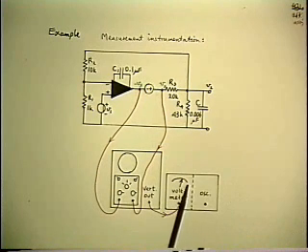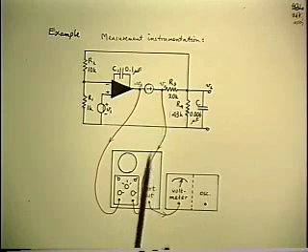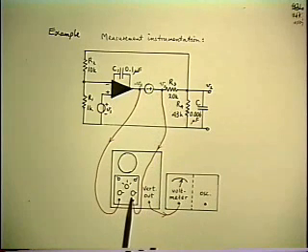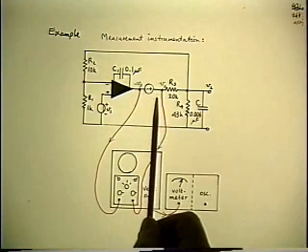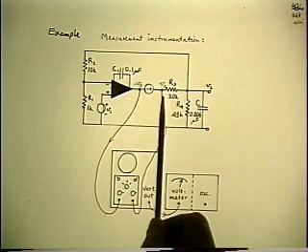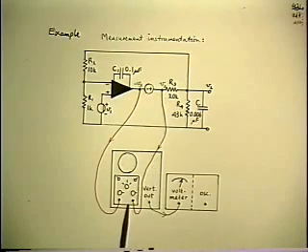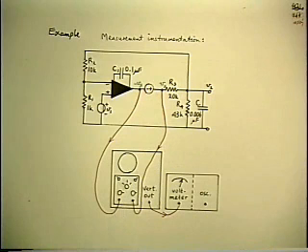That particular instrument. Most voltmeters measure only magnitude. So what I've shown here is another historical method, so to speak, of doing this. The two voltages we want to measure, the ratio, both magnitude and phase, which is the loop gain, is Vy over Vx. So I put both of them into a dual channel preamp for a scope. You can see this is historic because this represents an old 500 series Tektronix.